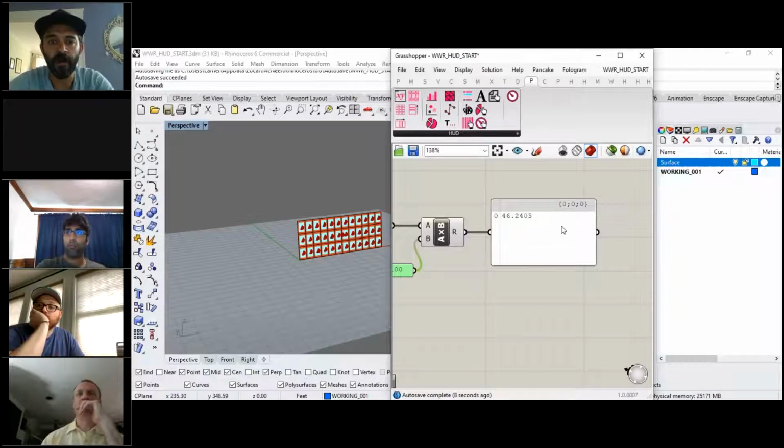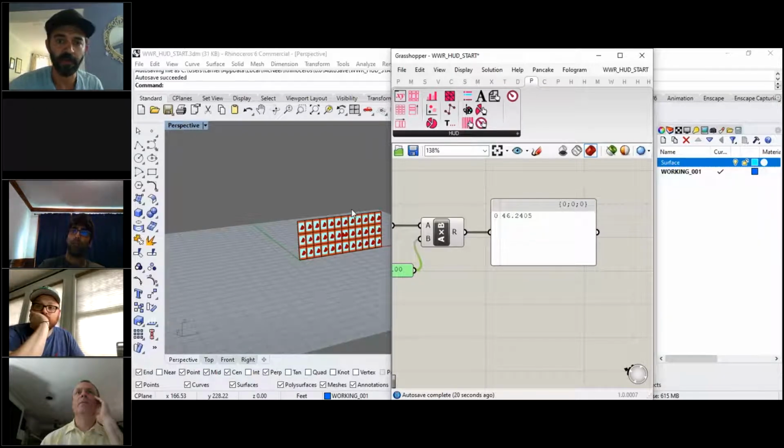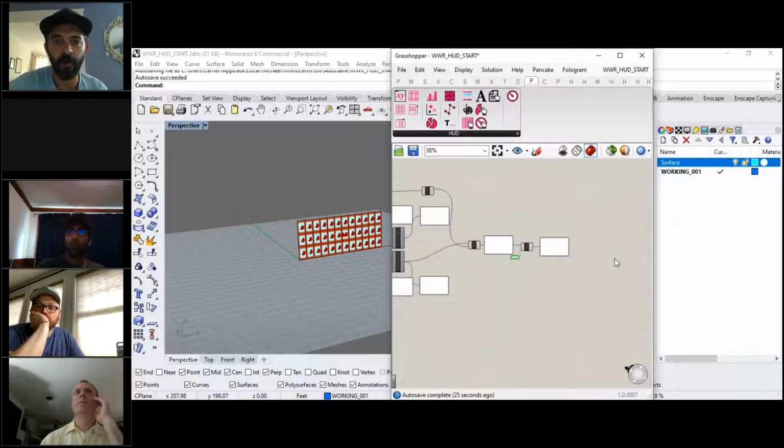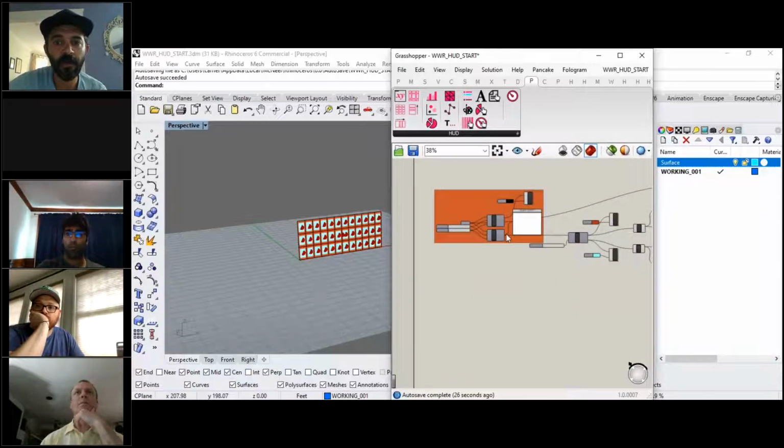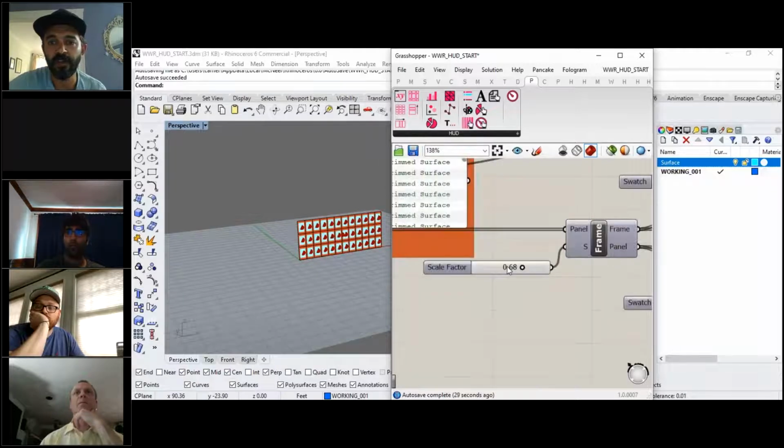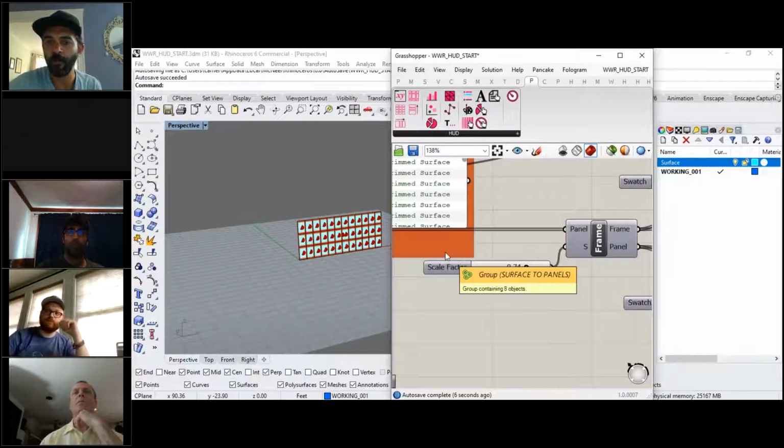So my goal now is to not have to look at Grasshopper. And while I make design changes here, whether it's the shape of the wall, I want to twist it and bend it, because you know I love to do that and get really weird shapes. And I want to see what that does to the window to wall ratio if I were to change the UV count, the size of the wall, even the scale of the openings. Because if I do this, I really can't see now what that window to wall ratio calculation is. Maybe I want to target a number like 20%.